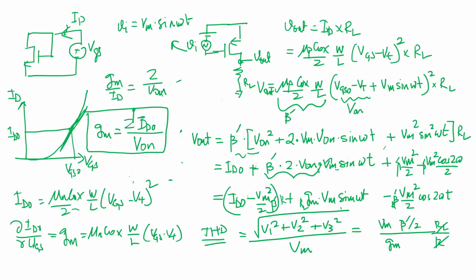Okay, so clear now, small signal and why we do small signal, and why you should be careful when doing small signal analysis or AC simulation. AC simulation always means it's the linearized one. That means it's about a bias point, and if your signal is varying so much that your bias point is varying a lot, then you have to rethink that. Okay, everyone is clear about this one.